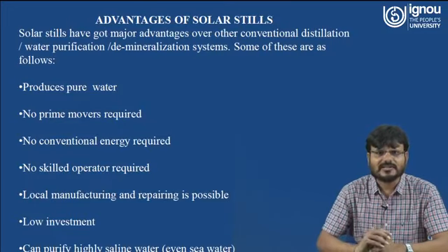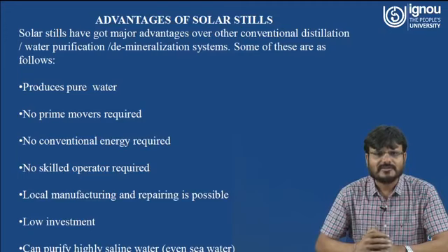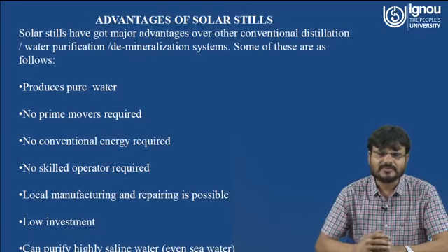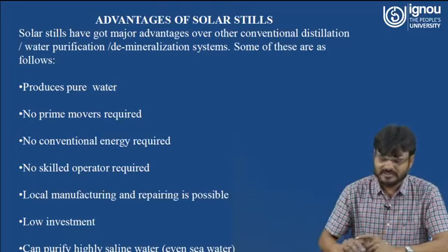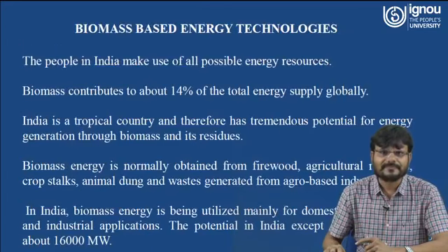Now what are the advantages of the solar still? First advantage is it produces pure water, no prime mover required, no conventional energy required because you are using solar energy which is free, no skilled operator required, local manufacturing and repairing is possible, and there is a low investment in this solar still.